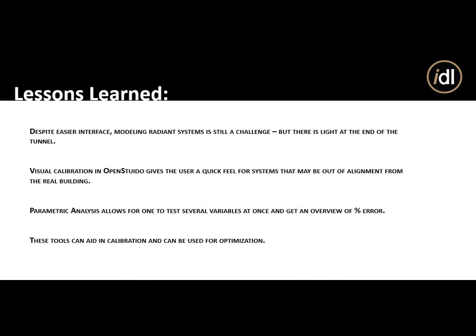So now with the Parametric Analysis tool, you can only import OSM files, right? Yes. You can't import IDF. No, you would have to import an IDF, turn it into an OSM, and then run the Parametric Analysis tool. So if you left OpenStudio to go to EnergyPlus to stitch in some HVAC systems that are not supported by OpenStudio, you cannot go back? No, you would lose the parametric analysis tool. You would have to do your own Ruby script on that.